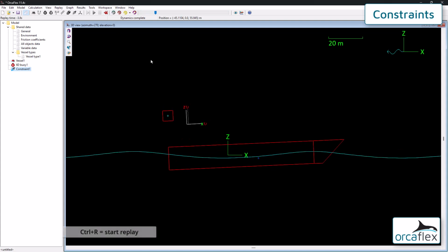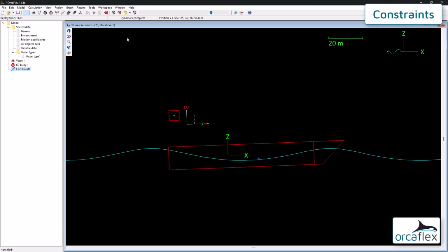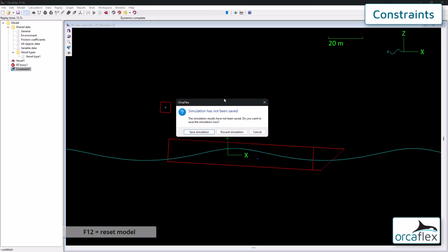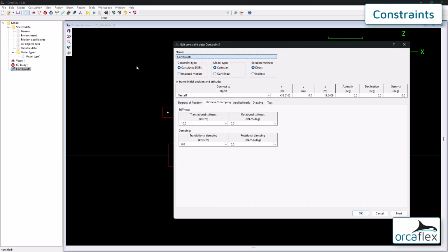And this results in a significantly reduced displacement. We can also apply nonlinear values using a variable data item. An example of this is to model physical stops at the ends of a sliding rail or the rotational stops on a Stinger roller box. Let's introduce a nonlinear translational stiffness now to this example.